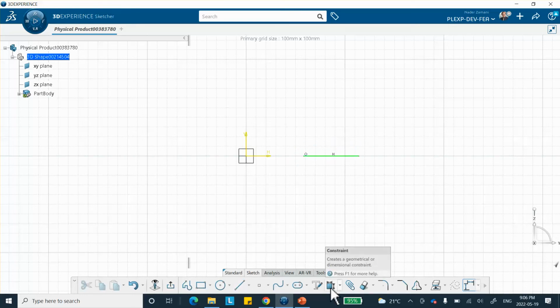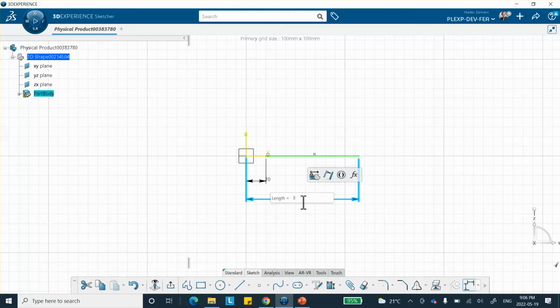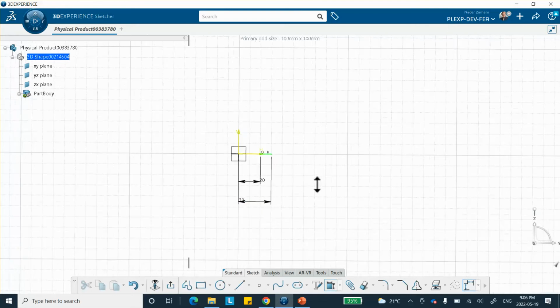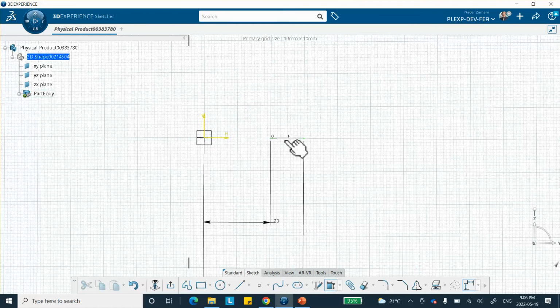and put the dimensions. So the inside radius of that disk is going to be 20 millimeters. The outside radius is going to be 30 millimeters. So dimension from this point to that axis. This is going to be 30 millimeters. There we are. So essentially we have this line, which is going to be eventually meshed with one-dimensional beam element and then declared as axisymmetric shells, which means virtually it's revolved around 360 degrees. Okay, so that's pretty much it. This is our geometry. We exit,